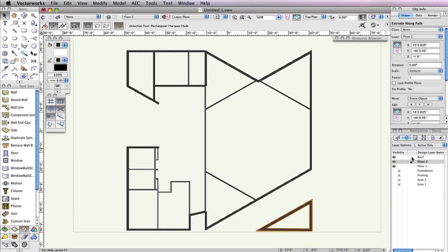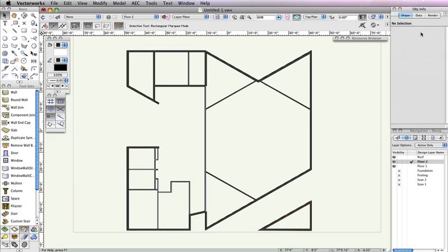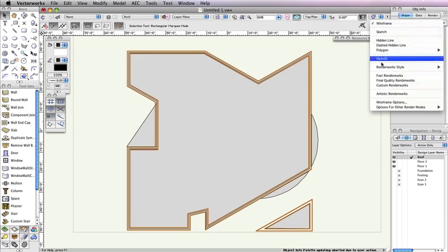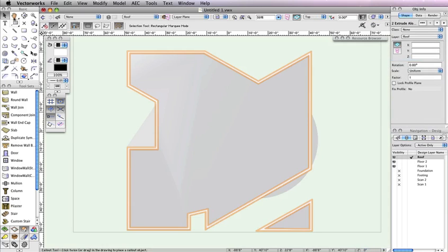Lastly, choose Roof from the Layer drop-down menu to move this extrude along path to the roof layer with the other roof objects and the roof flashing. You can verify this by making roof layer the active design layer, then rendering in OpenGL and using the flyover tool to see what you have so far.